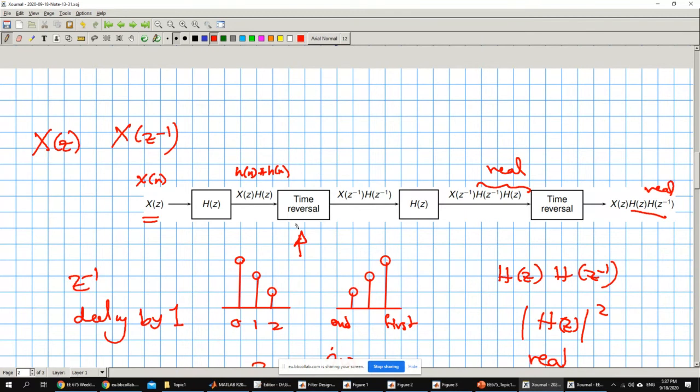If you have something like a real-time data acquisition system, like an ECG system, and you'd like to implement a filter that would process the data as they come in and produce the output to be displayed, you cannot do that with zero phase filters. Okay? Is that clear? Is the idea clear? Yes, yes.